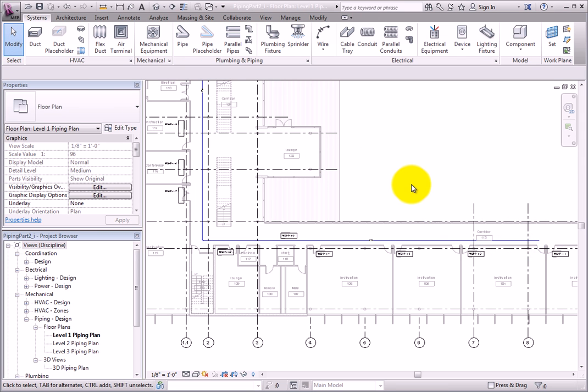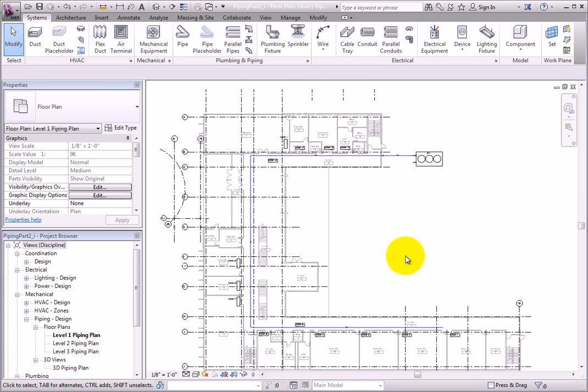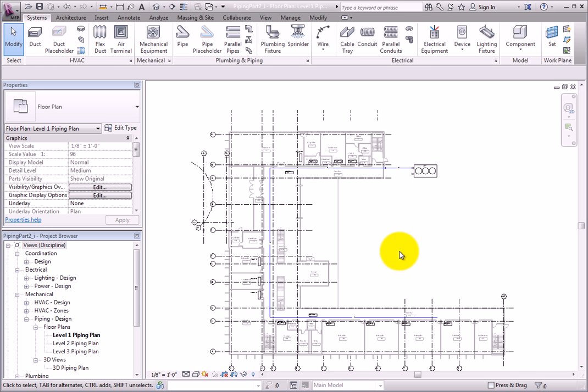As you can see, I used the same pipe diameter to create the entire main supply pipe, and I will size the pipe after the branches are connected. However, you could create several more pipe segments along the path and change the size as you go. The next step to laying out this piping system is to connect each water source heat pump to the main pipe. I'll zoom out and pan up to the north side of the building.